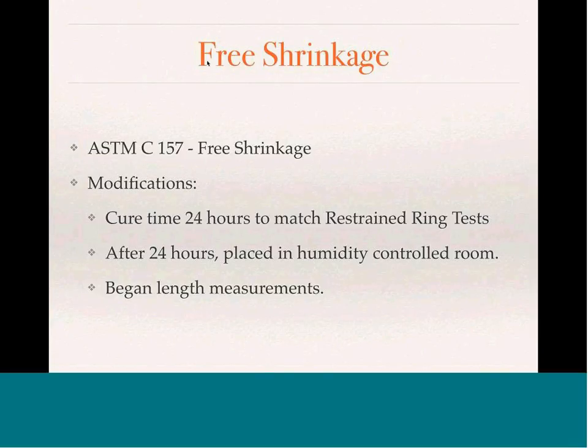The only modification we made to that method was we wanted to match the shrinkage testing to what we were doing with restrained shrinkage. So we cast the beams for 24 hours like we did the rings, then began testing on them right away, to make sure that everything was comparable in the duration.